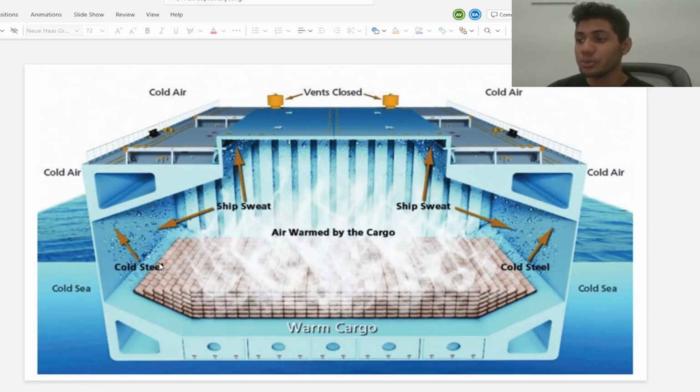According to a peer-reviewed article titled Review on the Impact of Marine Environment on the Reliability of Electronic Packaging Materials, it can be seen that moisture does not have a beneficial impact on ships' electrical components and hardware. The article says that high humidity conditions degrade the mechanical integrity and interfacial stability of electronic packaging materials, increasing their damage progression and ultimately severely compromising their long-term reliability in marine environments.